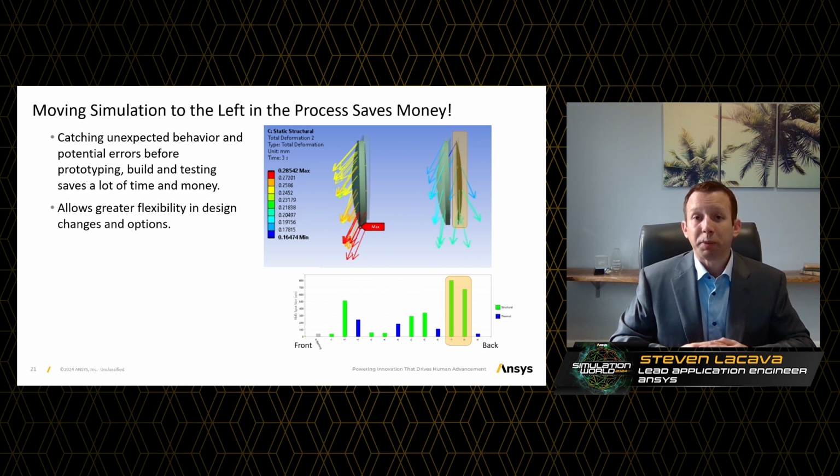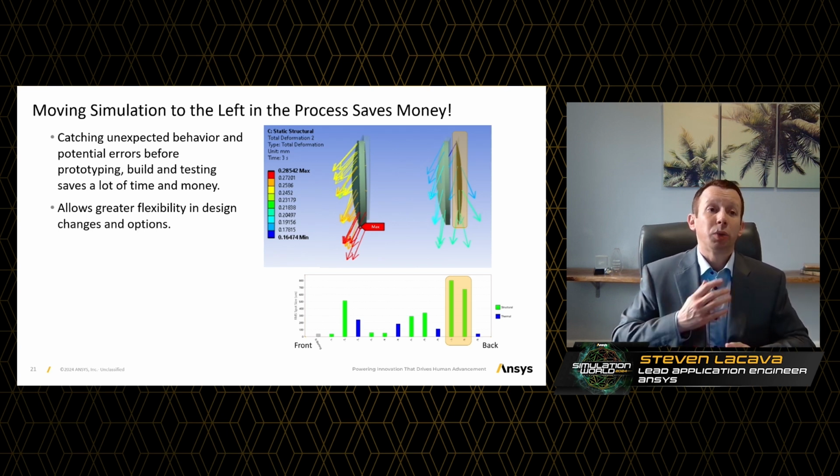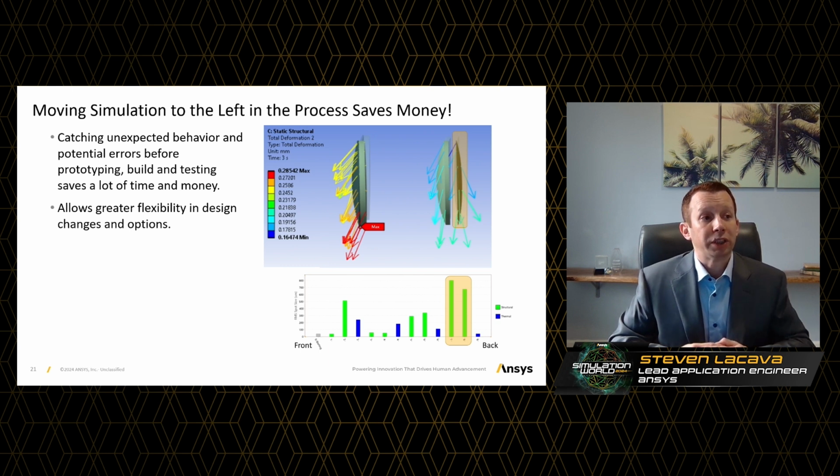Now, in this system, we expected the first lens to see the greatest thermal and structural deformations to the system. However, you notice that in terms of optical aberration, the last two surfaces, number 7 and 8, which represent the front and the back of that last lens, is actually causing the greatest optical aberration, even though it's the most protected. When we go back up to that image in the top there, which comes from Ansys Mechanical, we can see why. So even though the forces in terms of the intensity levels, those arrows are blue, not red in this case, they are weaker than that front lens.